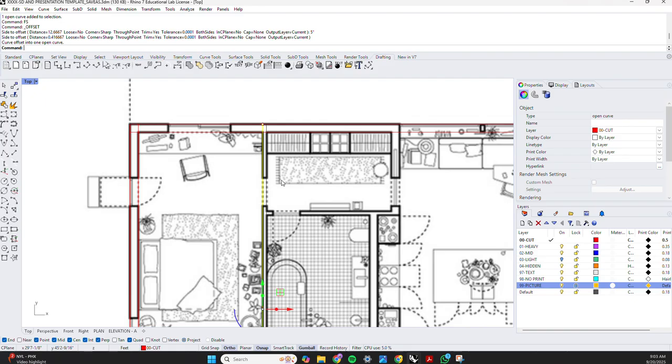What this will allow us to do is, down the line, thinking about making a physical model of this thing, a lot of sheet materials, like chipboard, all that kind of stuff, are sold in increments that double. So it's like 1/8 inch chipboard, 16th inch chipboard. And so thinking down the line, having one wall on the inside be exactly half of the exterior wall will make fabrication of our model a lot easier. So that's why I landed on that 5 inch increment.